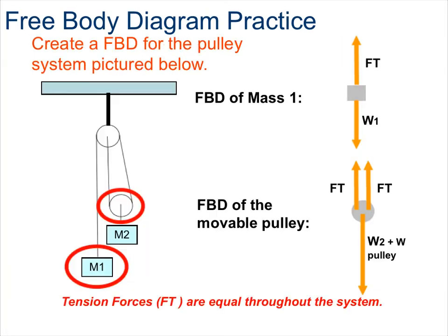force of friction. As you can see on this slide, free body diagrams are frequently used when solving pulley system problems. It's useful to isolate the parts of a pulley system to discover the relationships between each of the parts. This pulley system consists of an upper fixed pulley, which is supporting block mass 1, and a lower movable pulley. The movable pulley is supporting block mass 2. A single rope or cord connects these pulleys together. Keep in mind that both pulleys are going to be considered massless as well as frictionless.